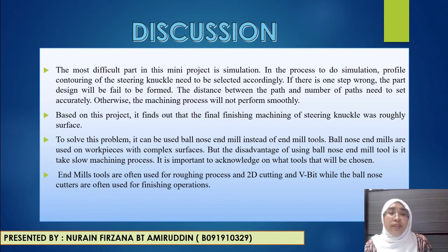Based on this project, we found that the final finishing of the steering knuckle had a rough surface. To solve this problem, a ball nose end mill can be used instead of flat end mill tools. Ball nose end mills are used on workpieces with complex surfaces, but the disadvantage of using a ball nose end mill tool is that it is very slow for the machining process.